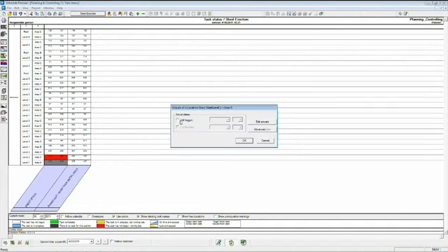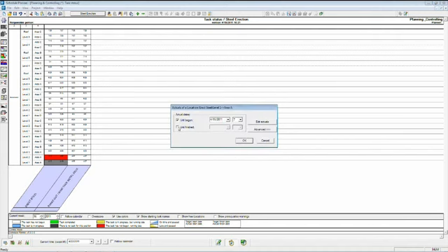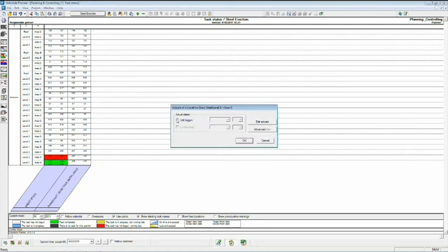Now, let's say we've collected our weekly actuals. We actually did begin on the 15th, and we did finish on the 19th as planned for location A. We can input that start and finish date. The control chart updates, tells us that task is completed, green is good. However, red is still bad. And the reason that our level 2 location A is still red is because we were supposed to have started on April 19th, and it's now the 22nd. We don't have a start date on this activity yet.